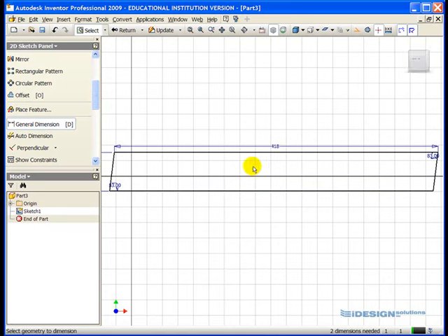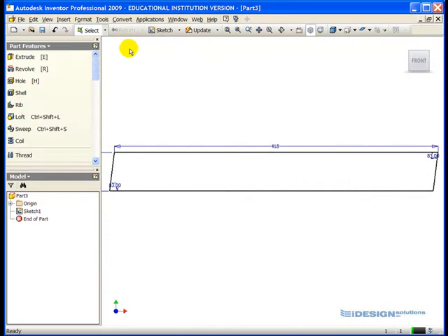I now want to exit sketch mode by moving my mouse up to the top menu bar, finding the return button. I simply left click. I want to place this view into an isometric view, so I move my mouse to the view cube in the top right hand corner. A house icon appears. I move my mouse over the house icon and I left click.